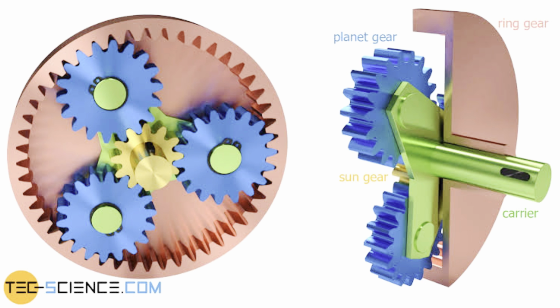If we unlock the sun gear and lock any 2 elements together, this will cause all 3 elements to turn at the same speed, so that the output shaft will turn at the same rate of speed as the input shaft. This is like a car that is in third or high gear. Another way that we can use a planetary gear set is by locking the planet carrier from moving, then applying power to the ring gear, which will cause the sun gear to turn in the opposite direction, giving us reverse gear. The illustration on the right shows how the simple system described above would look in an actual transmission.